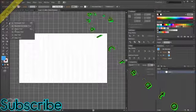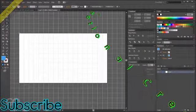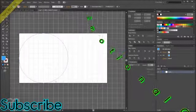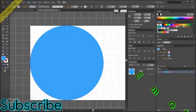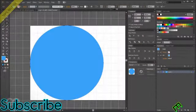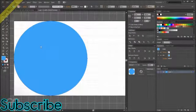So to create them, I'll take the ellipse tool, and starting here at the top, I'm snapping them exactly and creating it over here. So as you can see, the position of this ellipse is exactly given. It's starting at the origin 0 0, and it's exactly 100 pixels. You have to make sure you look at whether or not this is at exactly 100 pixels, because sometimes when you're trying to create it, the initial point might be a bit off, and therefore you might get a decimal value like 0.05 and such. So you have to make sure you're always looking at the transform values. Okay, so I have this object created.